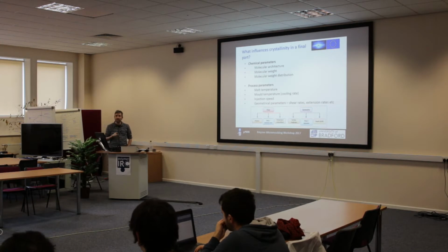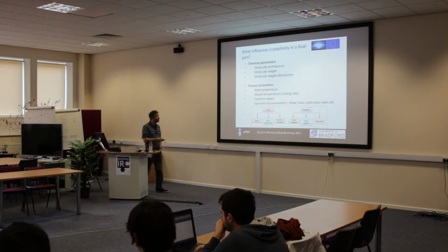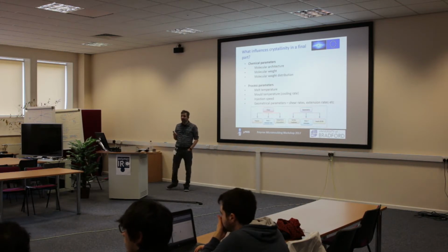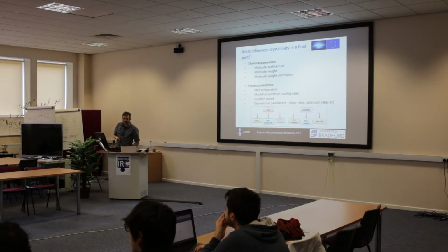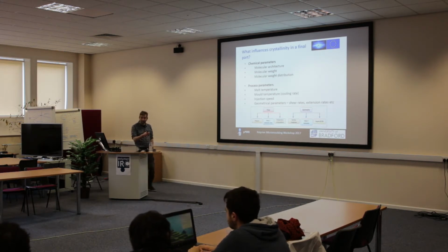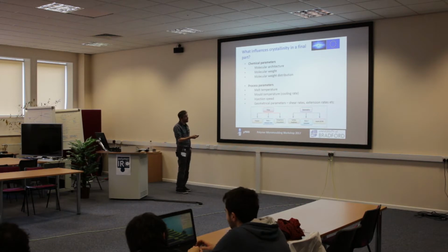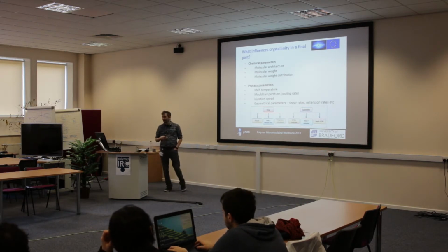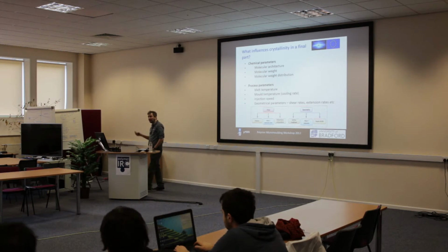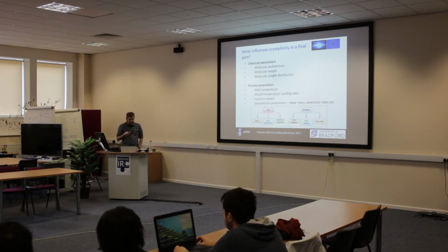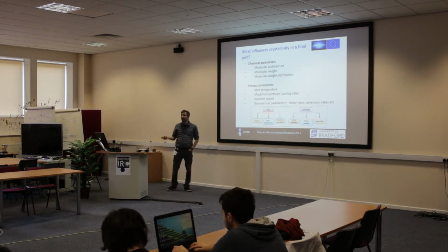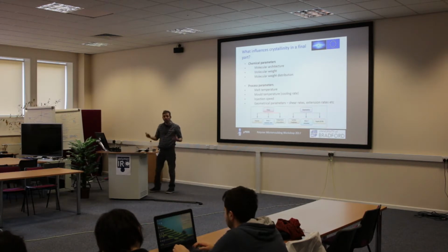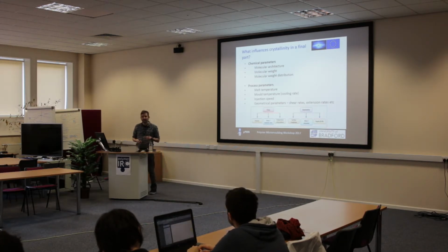We can control crystallinity through our mold temperature in a molding. We control through how we cool that material straight after injecting. We can control crystallinity by injection speed, i.e. the rheology of the material, because that's the flow and the resistance to flow, and also by geometrical parameters, by milling, by FIB, by whatever, to make whatever part we want. We can change our shear rates, our extension rates. We can change the depth. We can make it a more 2D part or a 3D part. We will all infer different crystallinity in our final sample.